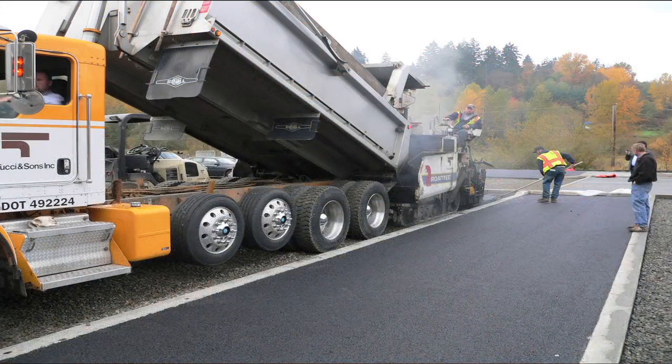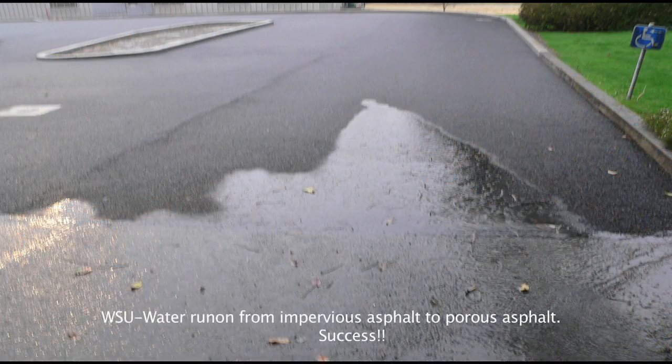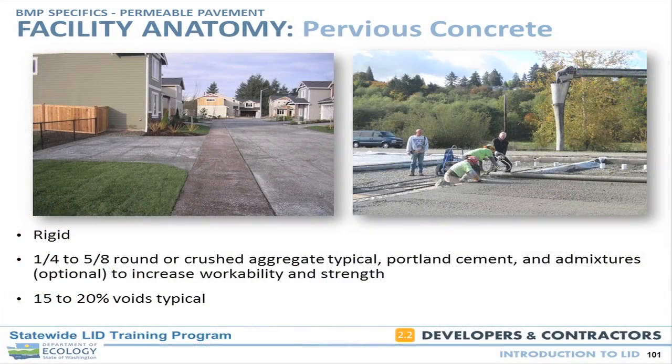But it can also be cost neutral with dense graded asphalt, which means that if you take out your catch basins and your treatment flow control, it can be quite a bit less expensive. But with the caveat that its durability and the practicalities of installing it, we need to have our eyes wide open on that. Porous concrete, which I think is probably the more common.